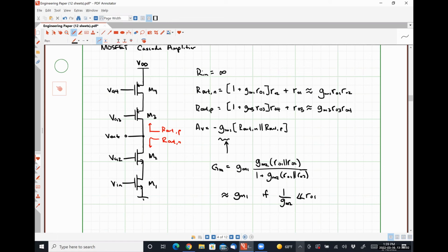All right, so what I hope to talk about on Friday is cascoded current sources. Now we're tying things back around, or cascoded current mirrors. So how we bias these guys practically, how we bias circuits with a high input resistance or high output resistance current source. We'll talk about cascode configuration, and then if we are constrained by headroom or whatever to only be able to effectively use single transistor based devices, we'll talk about the Widlar scheme and the Wilson scheme, which also have large output impedance.